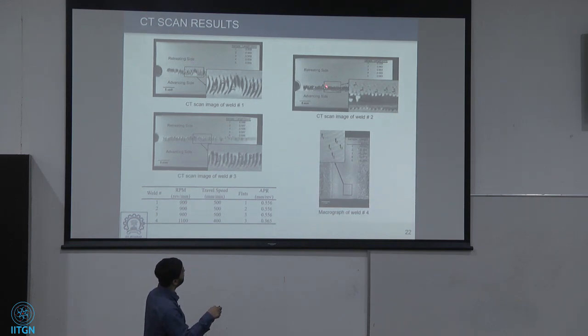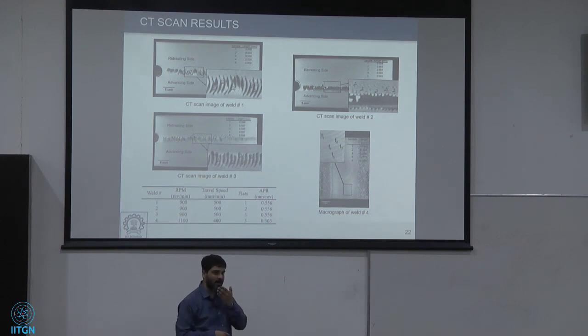You can see that with every revolution there is a chunk of material which is coming in. However, it has not been able to move all the way up to the end of the advancing side, and hence leaves an empty space, leaves the cavity unfilled at the area somewhere in between the trailing edge and the advancing side. Another very good feature which can be observed here is that the front edge of most of these uniformly spaced arcs are very continuous arcs.